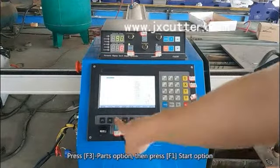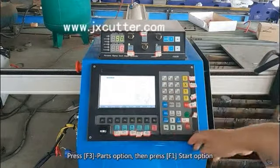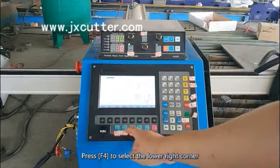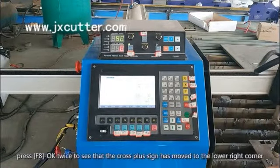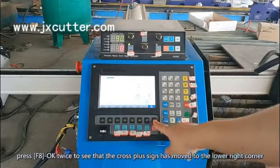Press F3 Parts option, then press F1 Start option. Press F4 to select the lower right corner. Press F8 OK twice to see that the cross plus sign has moved to the lower right corner.